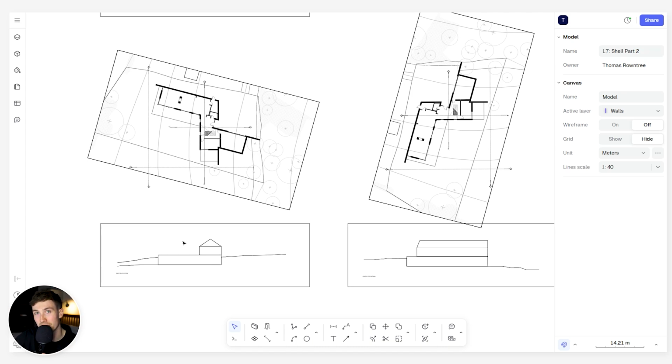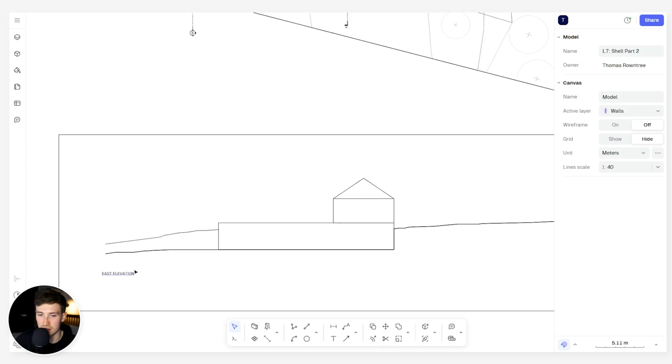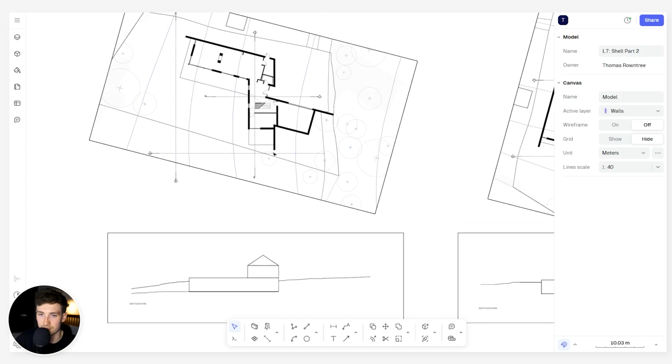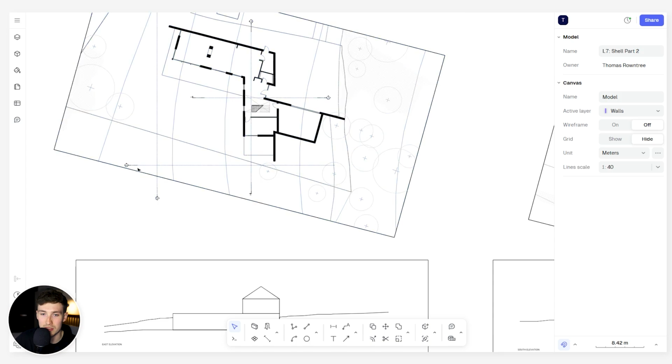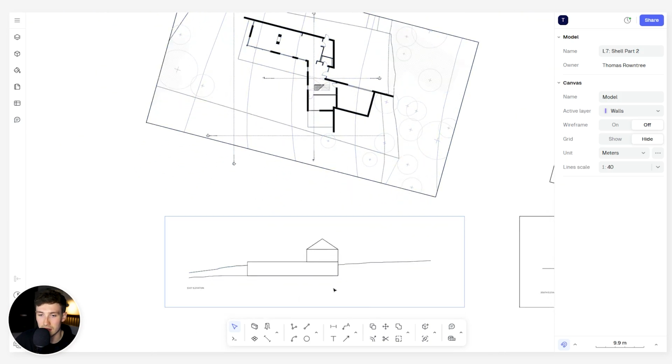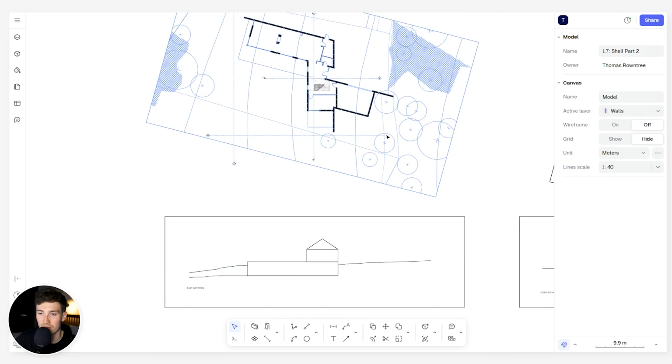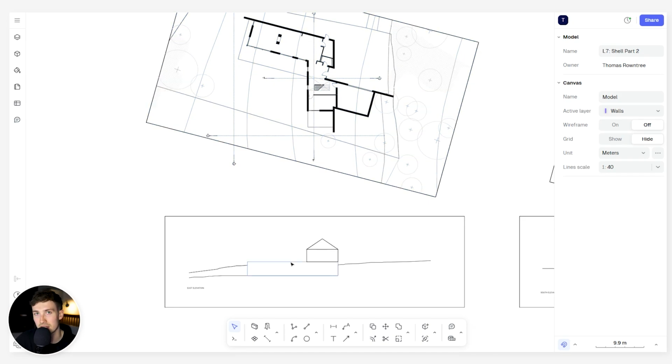And this will be a process of going back and forth between the floor plans and elevations, as I've discussed. And so what I've done here is I've set up the two elevations, the east elevation and the south elevation. And you're probably wondering why I've rotated the plans in this way, and it's simply because I have aligned the elevations parallel with the elevation line, so we can begin to essentially project the floor plan onto this massing and begin to define where these windows are being placed in elevation, where these voids, where these walls are being placed.